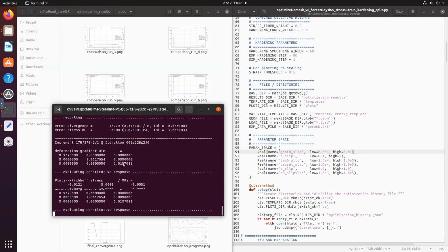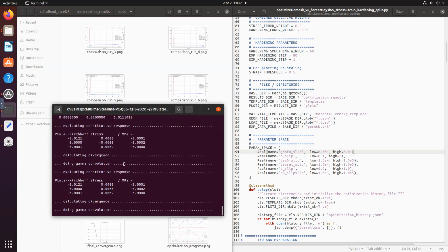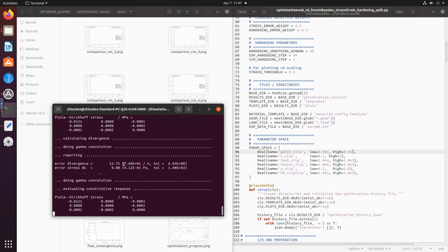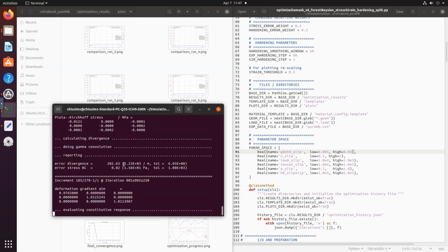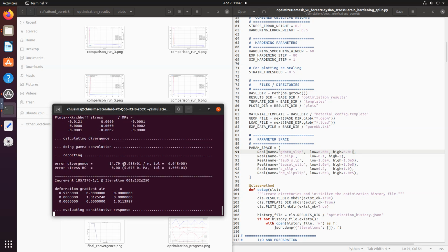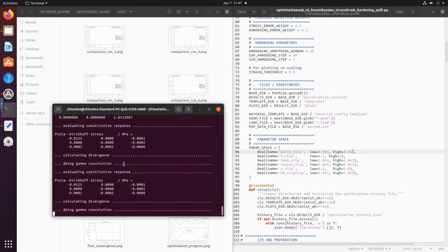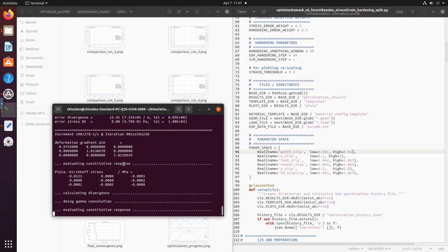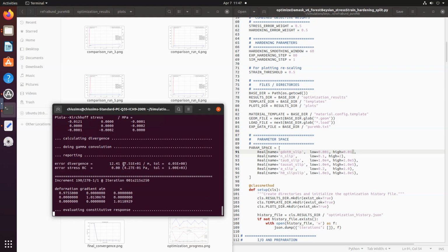And that is how you can save some time. If I let the simulation run for maybe 1000 iterations and then get the same outcomes, not a very good idea, right? So first I am just optimizing my time, running quick simulations in a much smaller window to see if everything is working fine, and later I will remove those comments. I will let it run for a larger number of increments, and the errors that I will get will be for the whole curve. For now, they are just for the small part that it is comparing. Let's see what we get this time.